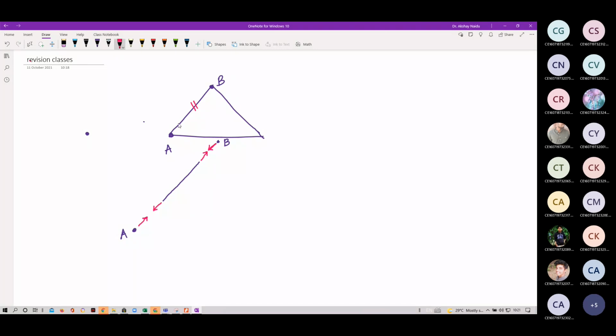So always in trusses, we write arrows like this. These are not forces on the members. These are the forces on the joints due to the member force. It will be the same. Let's say this is FAB. This will also be FAB. This will also be FAB. Writing member forces like this means we are assuming that the members are in tension, FBC. These are forces acting on the joints because we will use the method of joints.